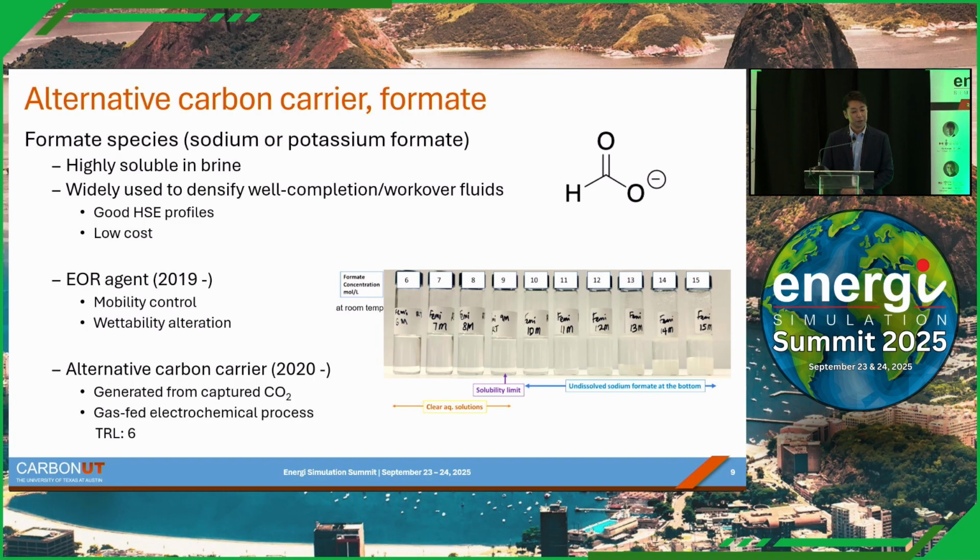So this means that because one formate carries one carbon, 9 moles per liter here means this sample contains 9 moles of carbon per liter of sample. So this carbon density of 9 moles per liter is close to the CO2 carbon density at the subsurface condition for some CCS projects. So we can carry a lot of carbon in this aqueous form, even at standard conditions.